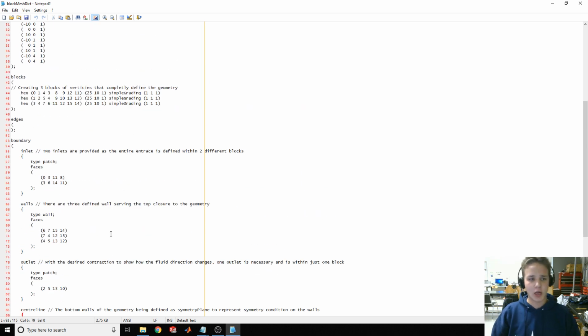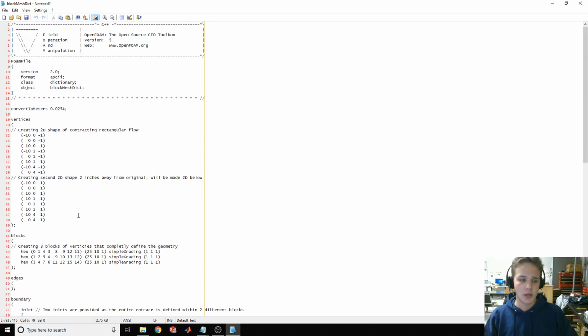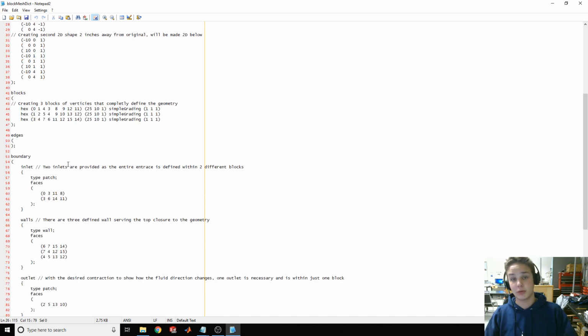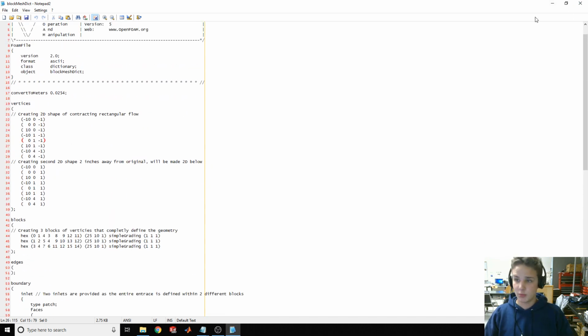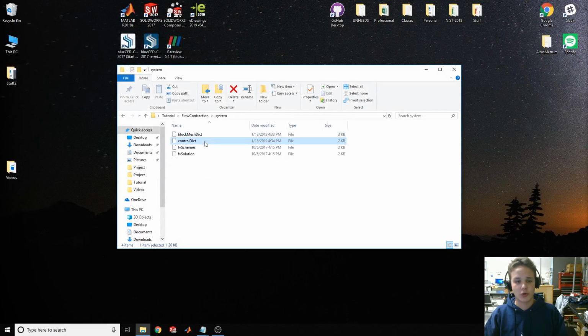So this is basically blockMesh, and I guess this is probably the hardest thing for a lot of beginners to understand: how these vertices go together, the boundaries. So feel free to watch this again if it'll help you, but there's also a lot of tutorials on this. So moving on, controlDict.